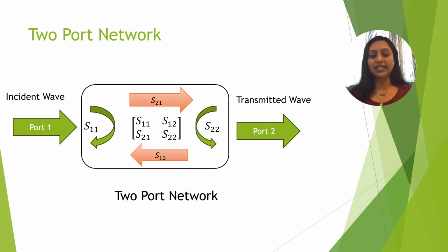All these are analyzed because these energies are scattered. When I pass a signal through a port, it gets scattered. This scattering is measured in terms of whether it is absorbed, reflected back, or transmitted. Since it's all about scattering, we call the parameter used to measure this S parameters, or scattering parameters.